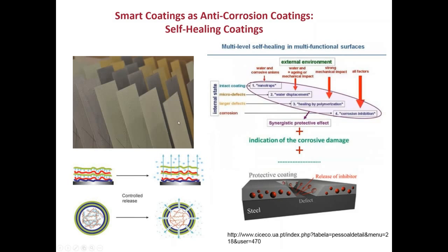So in the case of a coating exposed to the environment or scratch, or a corrodant reaches that of the metal to be protected, a smart self-healing coating can have a mechanism to release inhibitors or release sacrificial material that then can be used to restructure or modify the surface by releasing those inhibitors, and/or an autonomic healing in which you have diffusion or even polymerization of a material to reheal the coating.